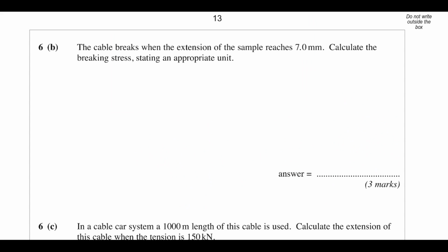Alright, so the cable breaks when the extension reaches 7.0 millimeters. So you calculate the breaking stress, and state an appropriate unit. So if we read off from the graph, at that extension, the force is 2.8 times 10 to the 5 newtons.